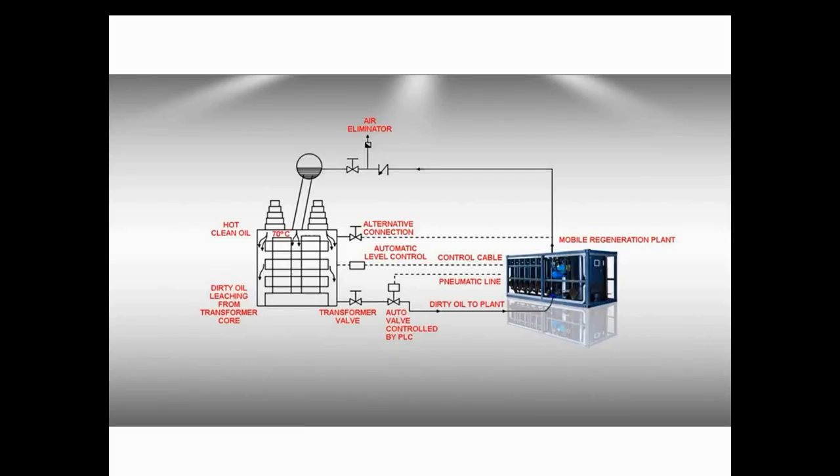New oils which can't mix with older ones shouldn't be used, to avoid probable contaminations. Silicon oils can never be mixed with mineral ones. If at least 10 ppm of silicon oil enters mineral oils, it incurs big problems for oil purification machines because high foaming will arise in the vacuum chamber.